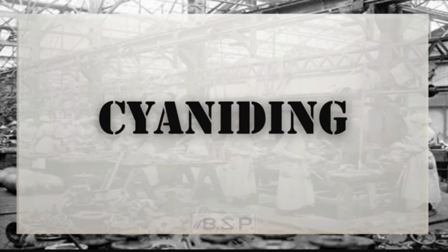The last type of case hardening process is cyaniding. It is fast and efficient. It is mainly used on low carbon steels. The part is heated in a bath of sodium cyanide and then it is quenched and rinsed in oil or water to remove any residual cyanide. This process produces a thin, hard shell layer that is harder than the one produced by carburizing. The major drawback of cyaniding is that cyanide salts are poisonous.